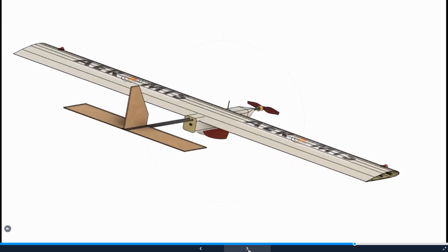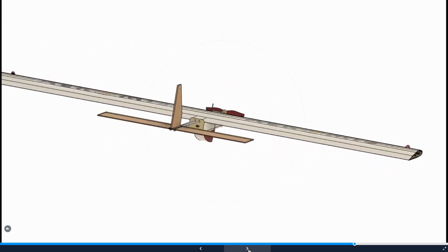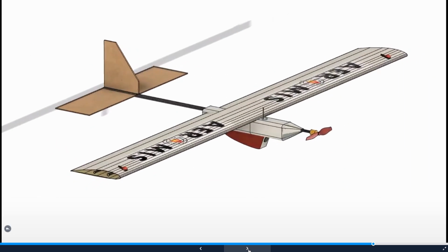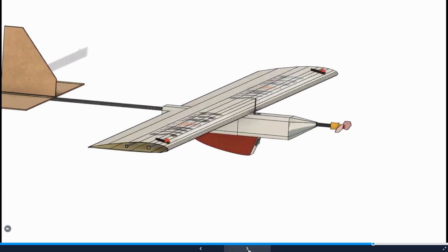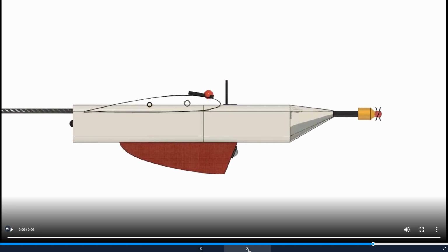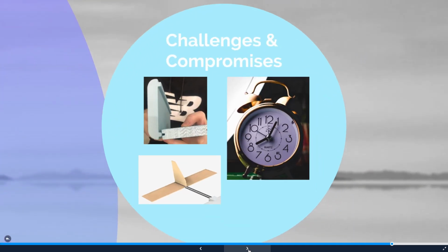The UAV has a high aspect ratio to enhance lift generation and glide capability with a lowered operating mass. The unassembled size allows the user to transport between sites with almost no difficulty. The thermal camera allows firefighters to understand the severity of the fire, as well as its direction and speed of spread, while also helping with spotting people through smoke or low visibility areas.